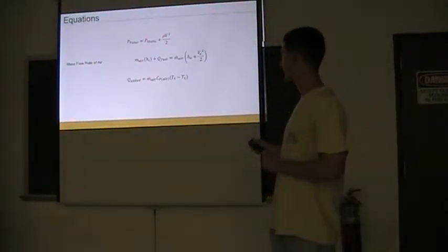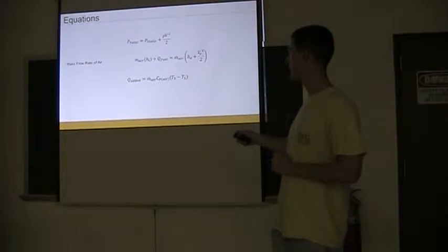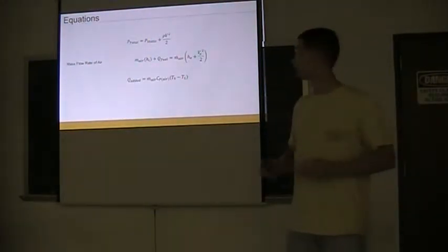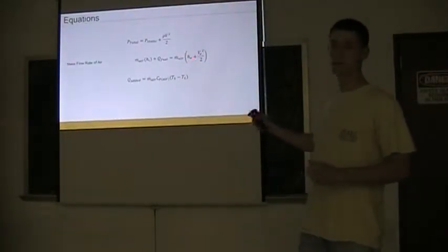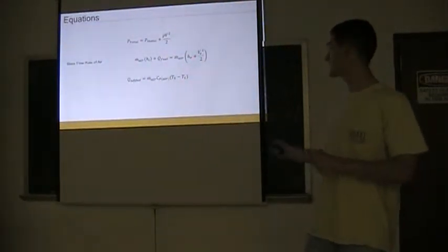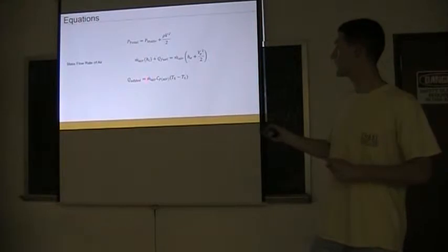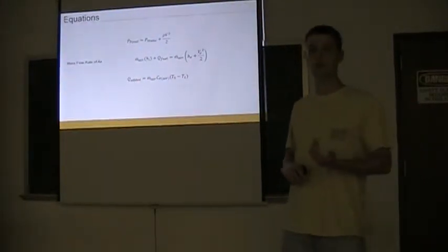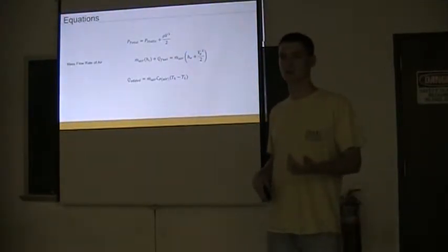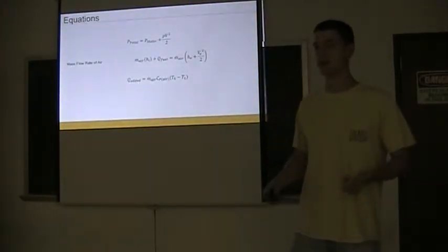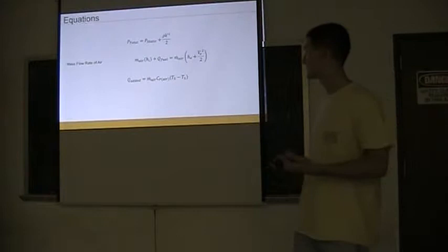These three equations here will be used to find the mass flow air rate. They'll take the pitot tube and the static pressure to find the velocity, back out the velocity, plug in the velocity, back out the mass flow air rate, and also they'll use that to find the heat added into the whole engine, and this will be used by the group reporter to compare to other different heats added by the different parts of the jet engine.